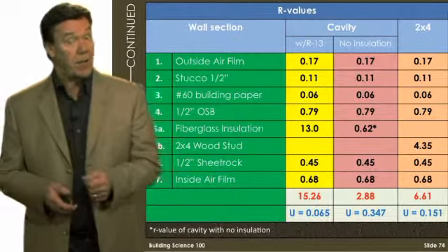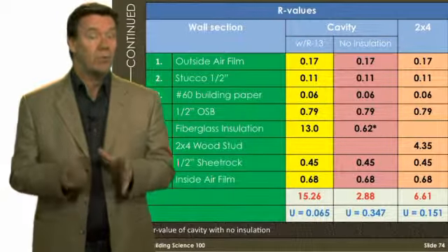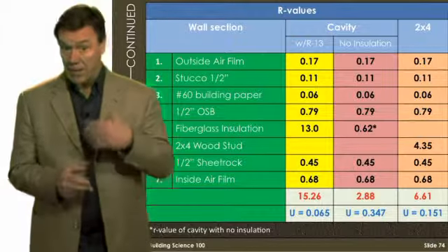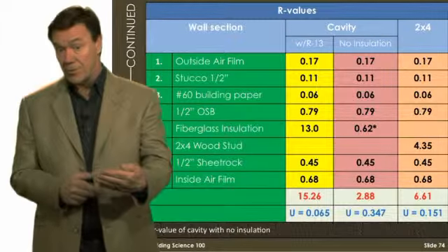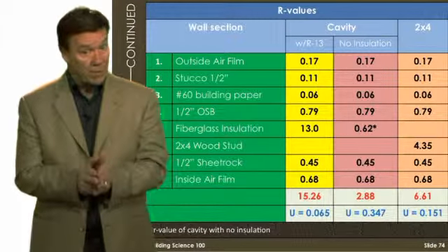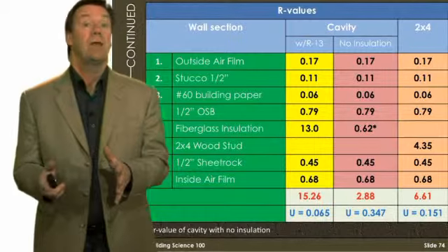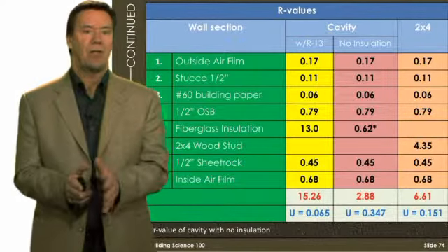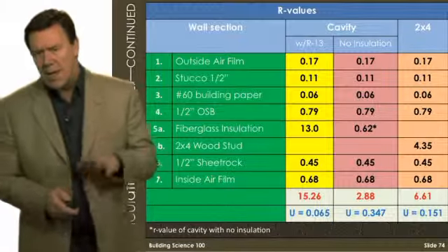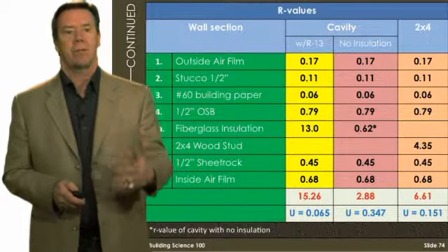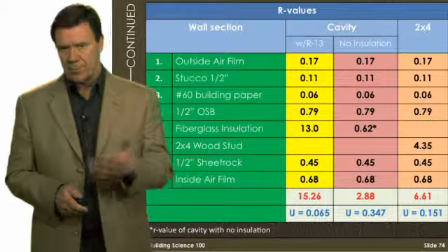Now, it's important to recognize that a lot of new building codes do not allow you to take the air film and all these other building materials into account when you look at the total cavity. They're really stressing now that you simply look at the cavity insulation and not add these other components. And that's largely because building materials vary so widely in terms of cladding systems.